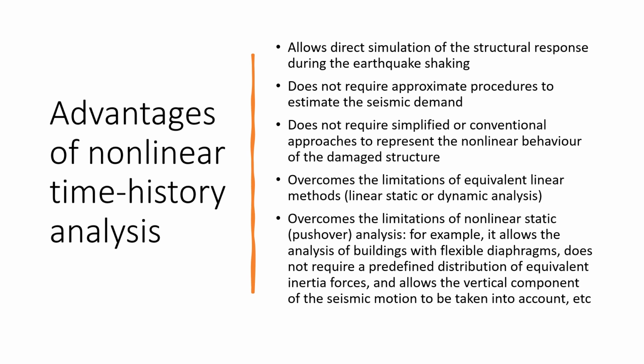It does not require the definition of a predefined distribution of equivalent inertial forces. And if you want, it allows to directly include the vertical component of seismic motion into the analysis, into the complete building analysis.